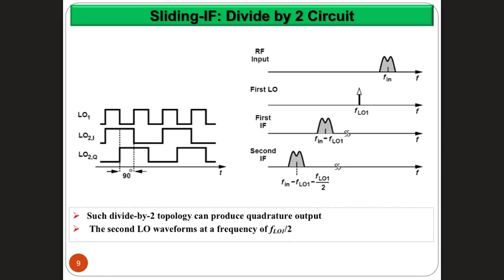Why do we use square functions? Because in oscillators, you can use a square function and then filter it to end up with a sine wave and a cosine wave. You start with a square function, put it through filters, and you end up with sine or cosine. That's how oscillators also work. Why did they shift by 90 degrees in the last one? Because it's the same oscillation frequency, but this is for the I&Q that we use to overcome the self-image effect.